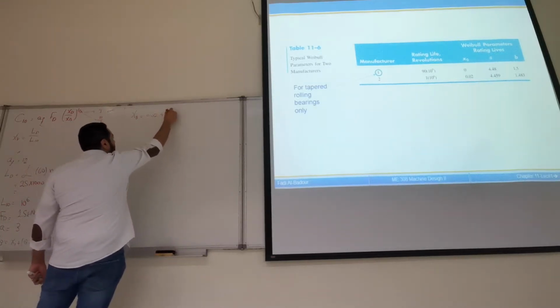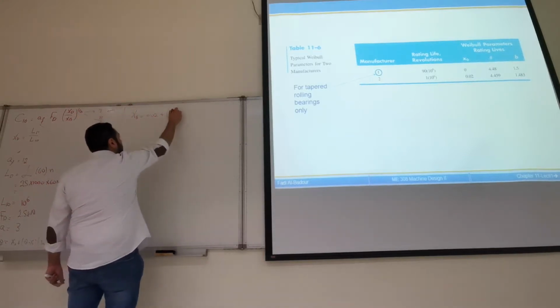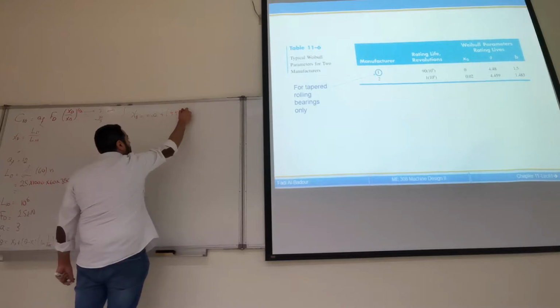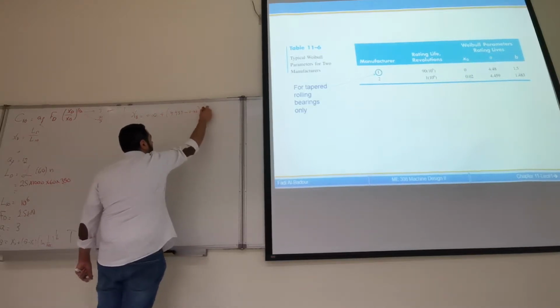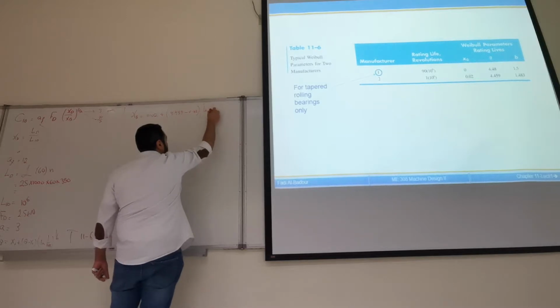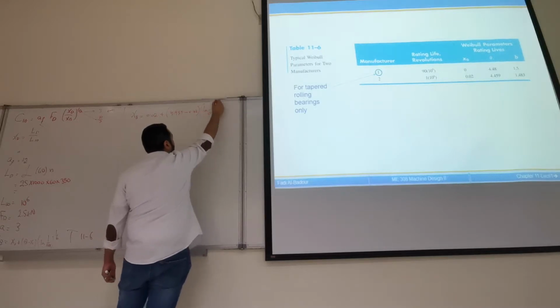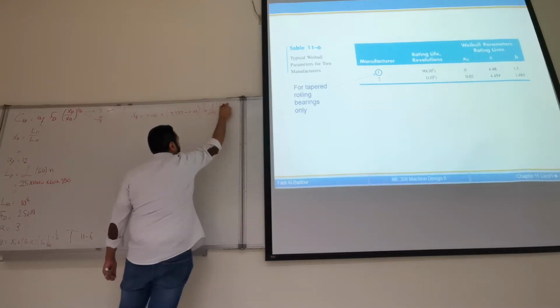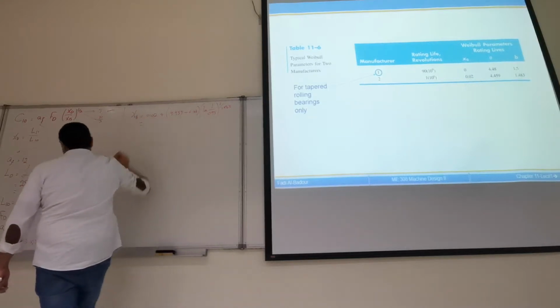So the values for those parameters: XP is equal to 0.02 plus 4.459 minus 0.02 times ln 1 over 0.95. Where did we get the desired reliability? It's a design requirement, so it's given in the problem. The power 1 over 1.483. Give me the value.